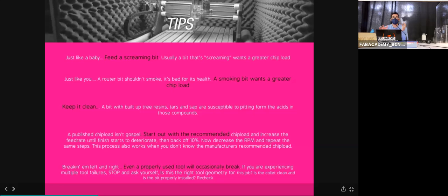It's important to have the dust collector on, the same as with the laser cutter, where we have the fume extractor. We are producing chips of material, so we need to take them out. Why? To help cool down the material. If you have too much dust on top of your material, that can also lead to a fire because it's accumulated material.